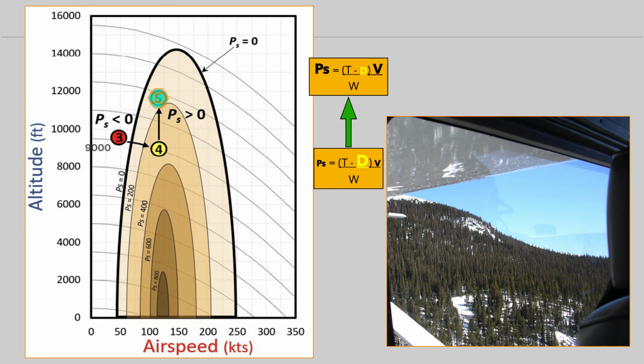Note you do not have to be over high terrain to encounter this type of scenario. For example, an unstable, slow, and low approach to landing, or high drag configurations during a go-round can lead to similar energy problems. In all cases, be aware of your current flight condition and compare it to the ideal for the phase of flight. Continually monitor your altimeter and airspeed indicators to obtain information regarding the energy state of your aircraft. This will help determine what options you have to manage the total energy of the airplane to achieve the desired result.